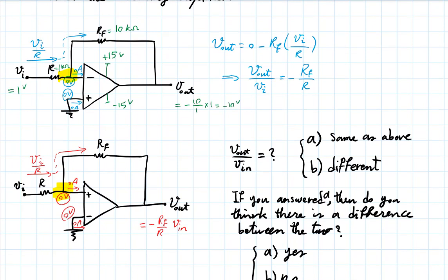So now I'm not saying, by the way, that this positive feedback is necessarily a bad thing. It depends on the application. There are great things that you can do with positive feedback. But if you're trying to make a non-inverting, an inverting amplifier like we've shown, the top one will work, the bottom one will not work, because you will always have some disturbance that will push this out of its equilibrium condition. Okay, so this is not a good circuit.